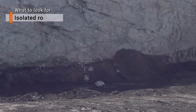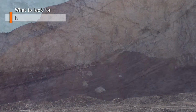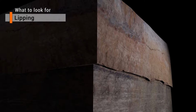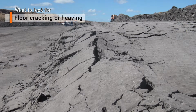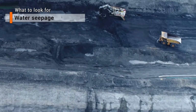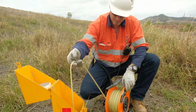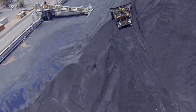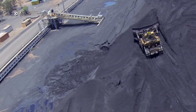Warning signs include isolated rock falls or loose material at the toe of excavated and dumped slopes. Lipping, which refers to the horizontal movement of strata in an excavated face along defect or weak planes. Crushing or spalling of coal representative of local concentrations of high stress, and floor cracking or heaving. A sudden increase or decrease in water seepage from a dumped or excavated slope face observed either visually or measured by instrumentation such as piezometers or standpipes. Water seepage from coal stockpiles is particularly critical for identifying the potential of failure in this type of dumped slope.